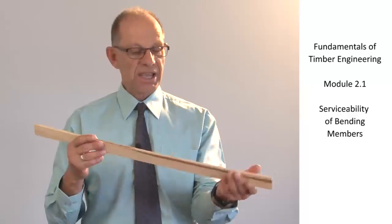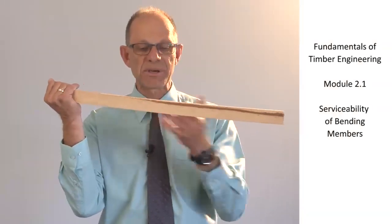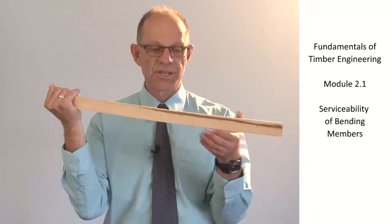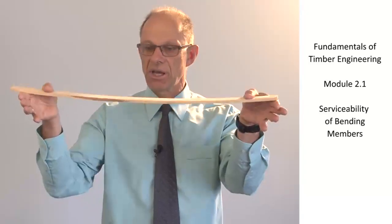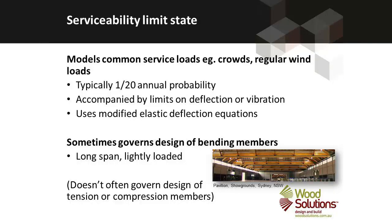Typically, the serviceability limit state uses loads that have a 1 in 20 probability of exceedance in any 1 year. Every time we look at the serviceability limit state, we're trying to limit a serviceability performance, a deflection or a vibration. So there has to be a deflection limit or a vibration limit. And we're going to essentially model it with elastic behaviour because we are modelling elastic response of the structure. Often the serviceability limit state does govern the design of bending members, particularly if the member is a long span and lightly loaded, typical of floors and roof structures.